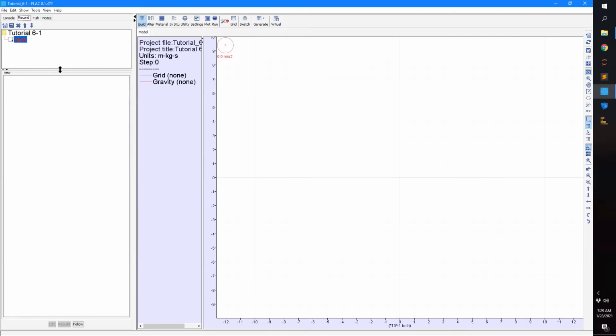The very first thing that we're going to do is develop our mesh. We don't need to use the virtual grid in this particular case. It's going to be rather simple for us to create it. But one thing that is going to be quite important is that we need to pick our element size appropriately. One component is that we expect high shear strains in the clay relative to the dense sand because it is softer.